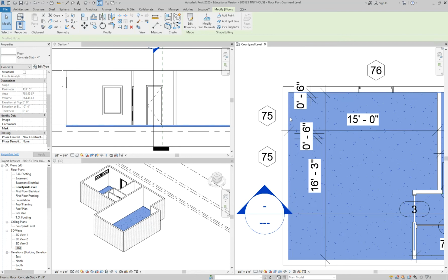I just want to make sure you guys can find it. So I'm just hovering, right? Tab once. There's all your walls. Tab again. There's your floor. That line is your floor. I wanted it to go blue. Not yet because we're just hovering. You have to click on it before it goes blue. Oh, the perimeter is blue. Okay, one more time. There you go. Now click and it's selected. So I'm being dramatic. It's not that big of a deal.